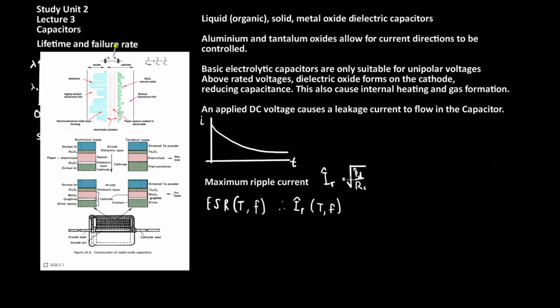Like all devices, a capacitor does have a power rating. A capacitor which operates in an AC environment will have some AC ripple on the current and voltage across the terminals of the device. The peak RMS value of this ripple cannot exceed the maximum rating for the device, or the device will start to degrade or experience catastrophic failure.